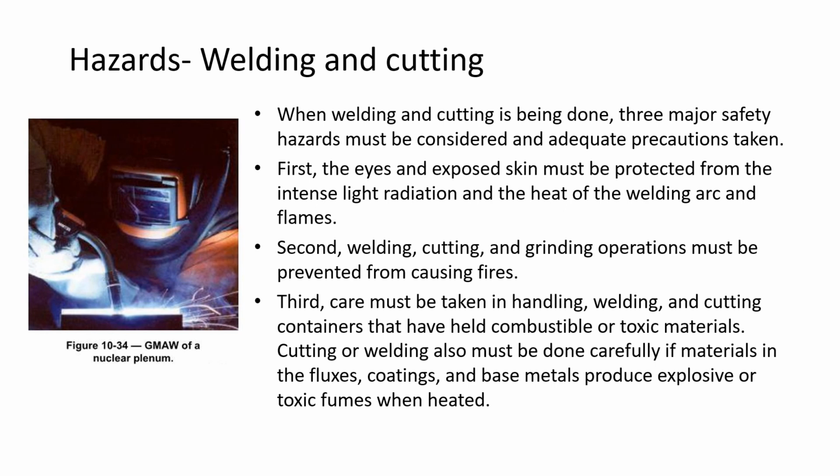Cutting or welding also must be done carefully if materials in the fluxes, coatings, and base materials produce explosive or toxic fumes when heated. So, yeah, sounds like a lot of fun. But these are things that we can deal with. We just have to mitigate and understand what the hazards are before we strike an arc, and make preparations for these hazards, and then we go from there.